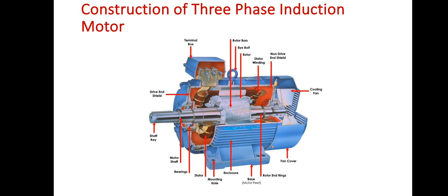Apart from this, the machine has a central shaft. After that shaft we have the rotor part. The rotor part for a squirrel cage machine has the two end rings which are connected at both ends of the rotor shaft, and the rotor also has the bearings. The rotor has its own slots and the rotor winding.